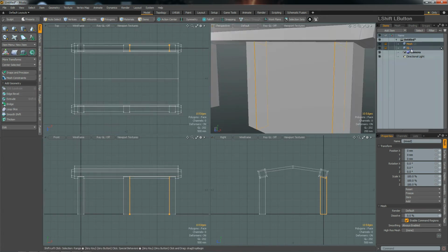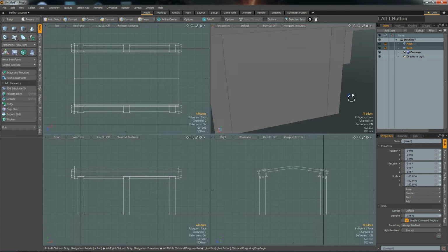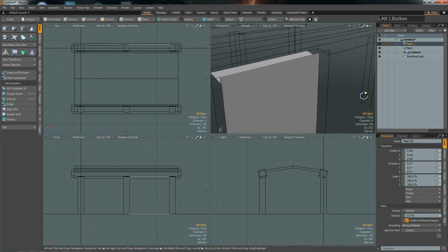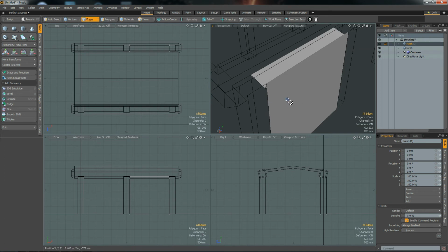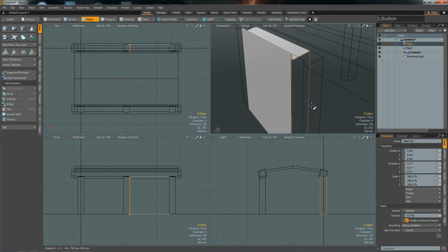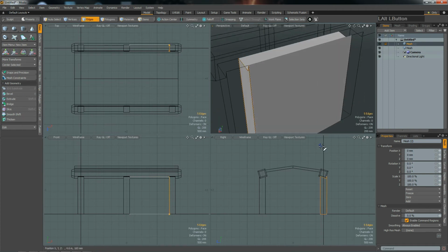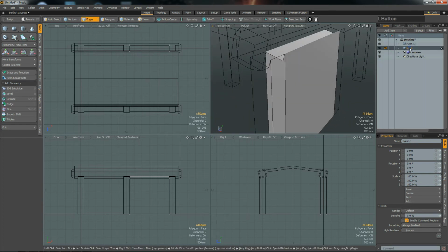And there we would have a full going wall through with no indentations. So we could even use this as a wall making method. Remember when I bridged this, I selected for remove polygons. That's why the edges here have no polygons, but if I select this edge loop and hit the P key for polygon, then they are right there. So yeah, that's one way of creating wall segments.